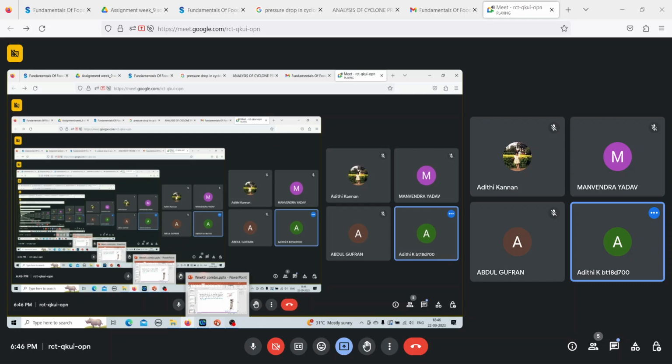So what a clarifying filter is, is that you have a filter medium with all these pores. Now these pores will not be as straight as shown in the figure here. It will be long tortuous pores. So when you're passing slurry through a clarifying filter, all your particles will actually be smaller than those of the pores. So it will easily go inside the filter medium. So all the particles will go inside the filter medium, but because of these long tortuous pores, these particles at some point will get stuck inside the filter medium. And what you receive at the other end will be a clarified filtrate.